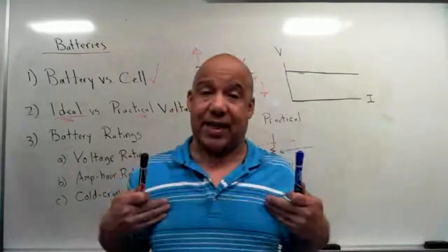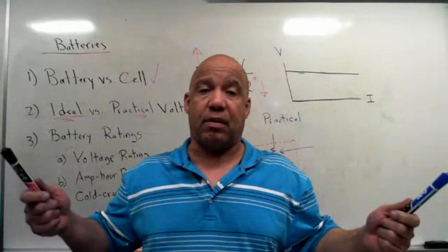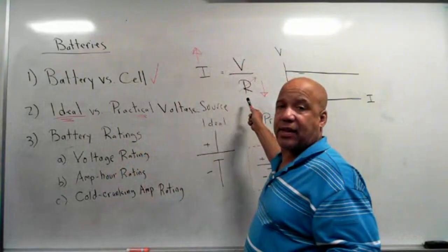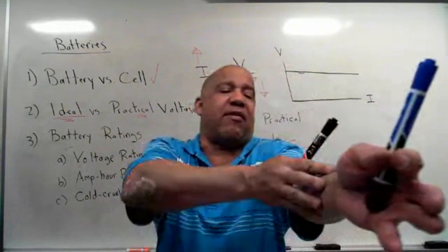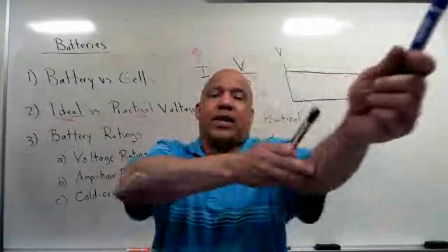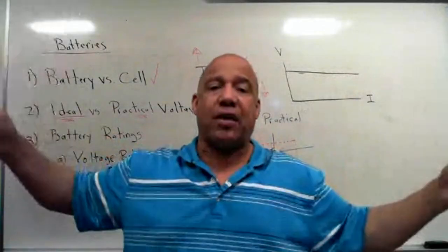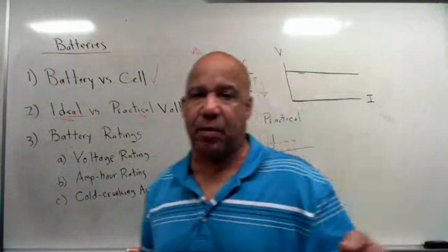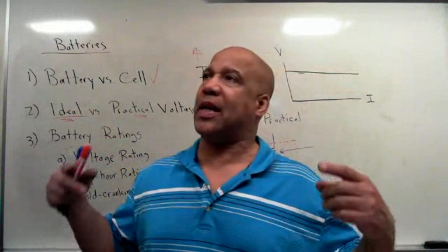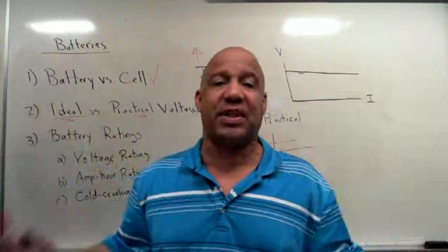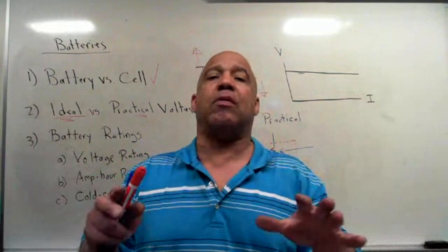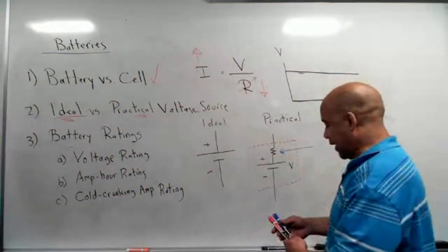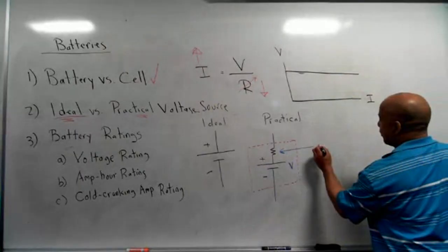You're measuring the resistance of your body, at least across here. That doesn't mean if you open up your chest, you'll see a little bitty resistor inside of you. You're measuring all the resistance of all the biological material between these 2 points. You can draw that as a resistor. Well, here the battery is made up of chemicals. If it's a car battery, there's lead plates in there. All that stuff has resistance. So you can lump all that resistance together into this symbol, and that's called the internal resistance of the battery.